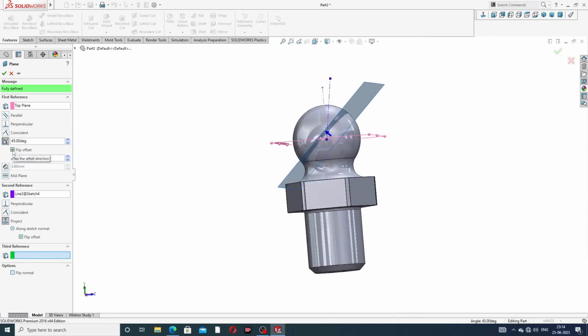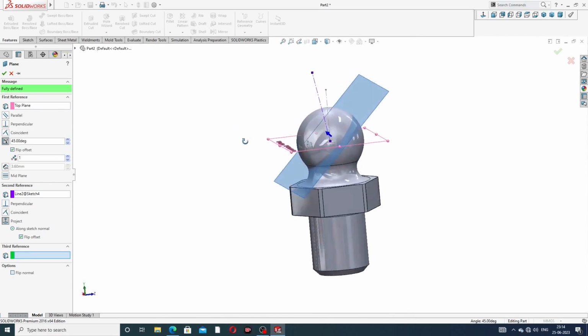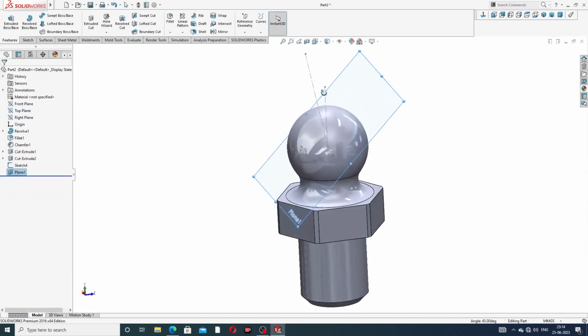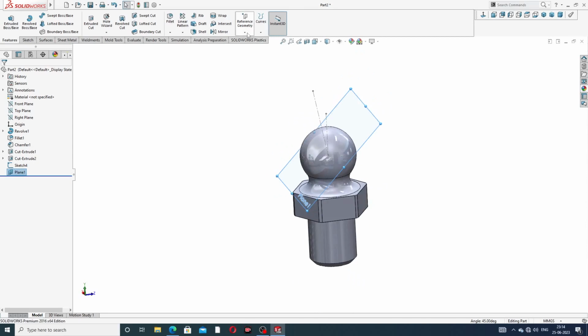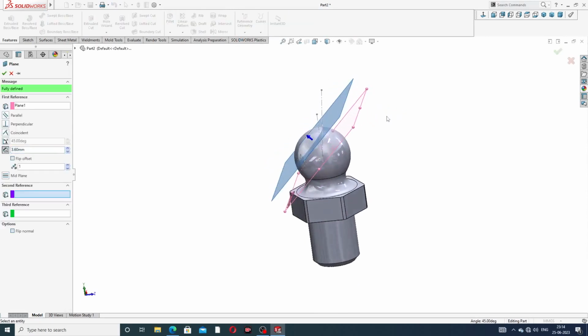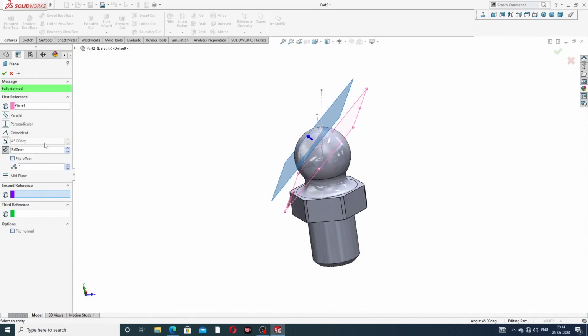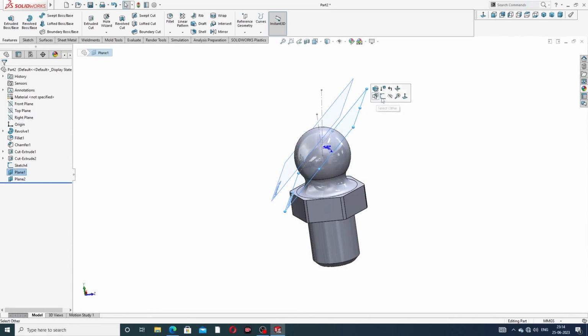Okay, and use all is perfect and click OK. And next is again select this plane and use this, again select a plane, and this distance is 3.6 millimeter. Okay, this 3.6 millimeter is extrude cut. Again select a 3.6 millimeter and click OK, and this plane is hide.